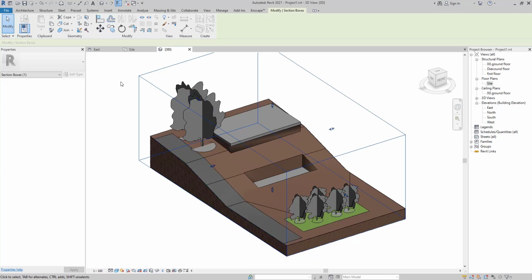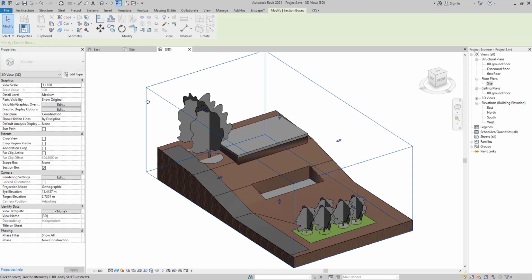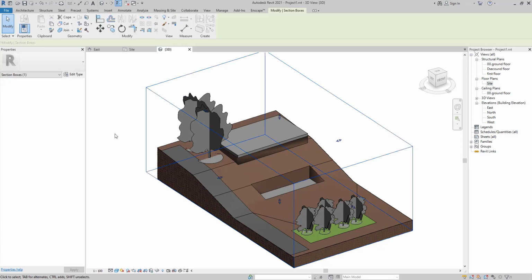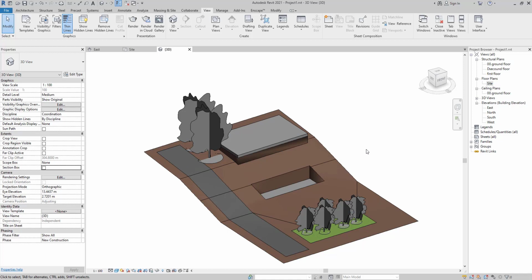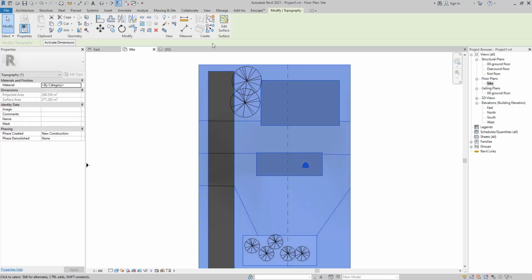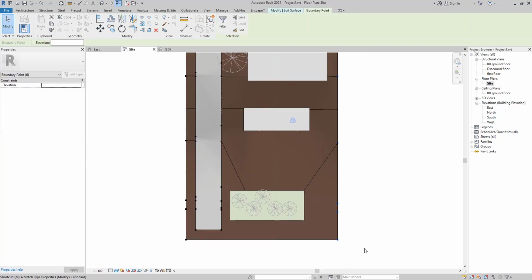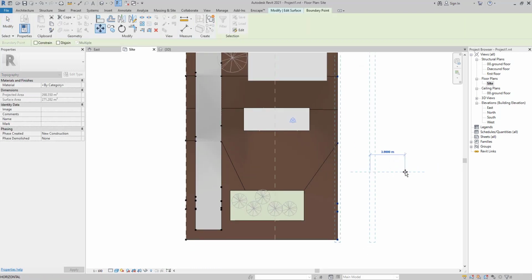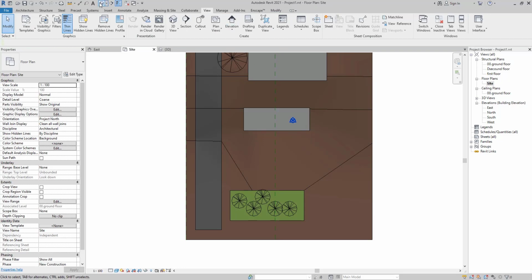One of the points which I want to mention is that when you hide, for example, your section box here, you are going to deactivate it. It will be removed, any setting will be removed. And the thing which I wanted to mention, if you go here, for example, to make your surface bigger by clicking on these points, moving, your section box is going to cover all of your project again.